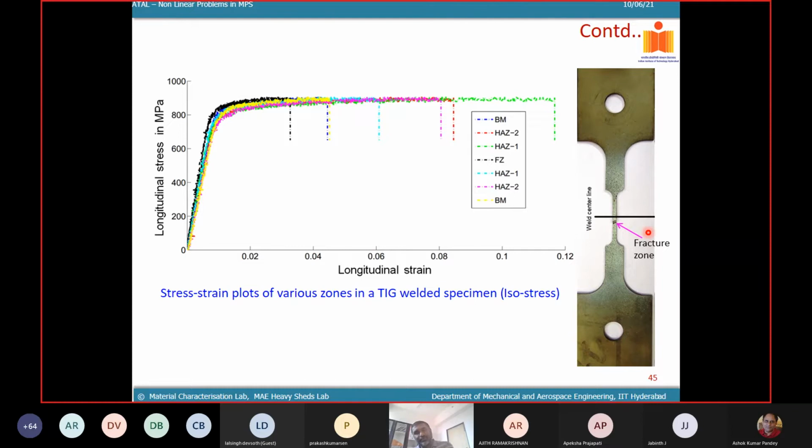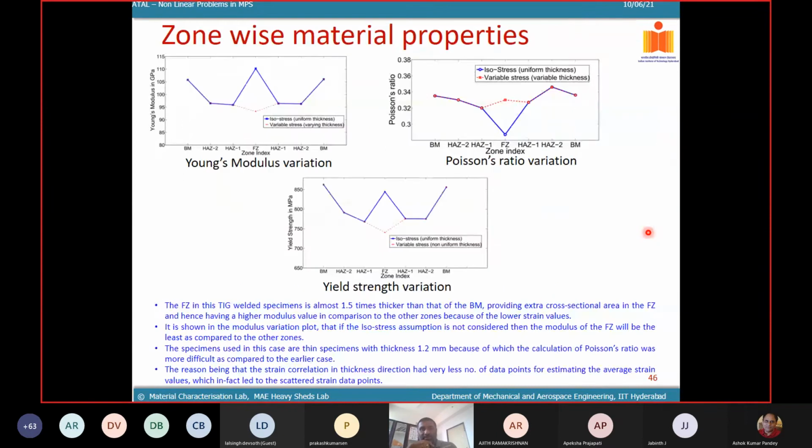And so this is also a curved sample. Okay, this is because they have taken it from a casing, from a static part in a turbine. So this is a curved sample. That is why we have cut using wire cut EDM, and then we have put a clevis so that the self-alignment is there and your loading would be more accurate. And similarly, the zone-wise properties.